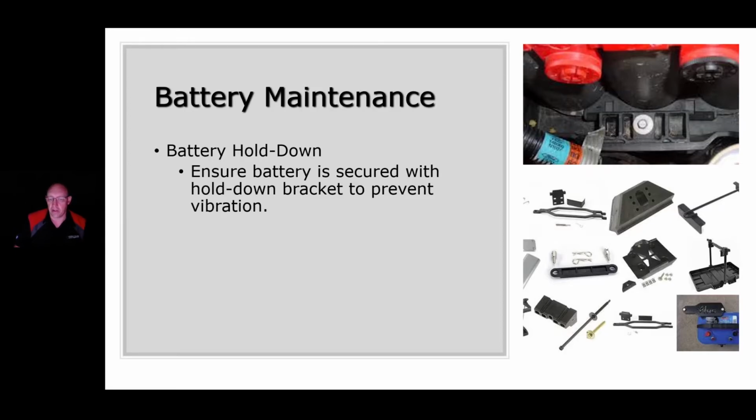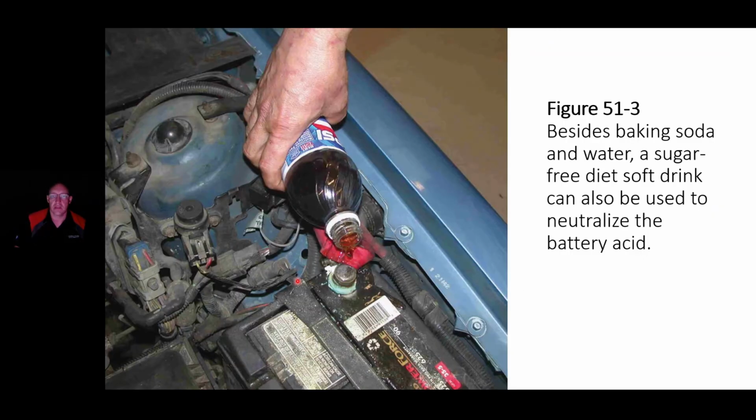So moving on to our next slide. Using Pepsi, very good idea. Using Coke, it works, guys. It does work. I don't know if you want to use what you drink and lose your beverage, but like I said, Monster energy drinks are phenomenal at cleaning battery terminals. It makes them look brand spanking new, guys. It's a really crazy thing, but it does. Makes me wonder if you want to be drinking that stuff and ingesting it when you see what it does to a battery terminal. But it's good. But baking soda is the best thing.